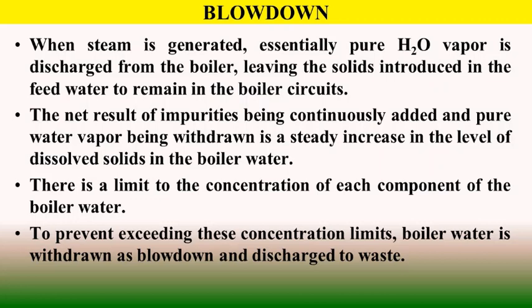Now to prevent exceeding specified concentration limits of impurities, boiler water is withdrawn from time to time from the boiler water steam drum as blowdown, either intermittently or continuously, and discharged to the drain.